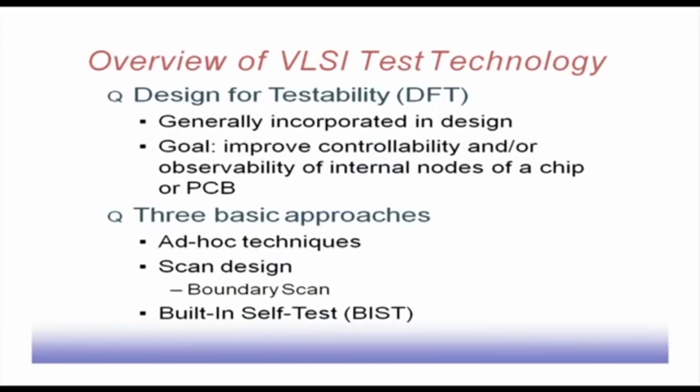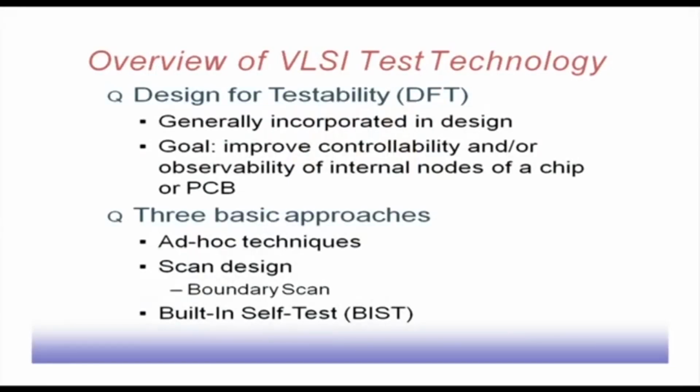easy. Now, this DFT is generally incorporated into the design, and the goal is to improve controllability and/or observability of internal nodes of the chip, or it may be for PCB also. In the PCB also, we have got a number of chips mounted on the PCB, so that individual chips' inputs and outputs may not be traceable. So, we have to have a look at that from the system input output point of view. So, we may need to have some feature incorporated in the PCB also, so that it becomes testable.